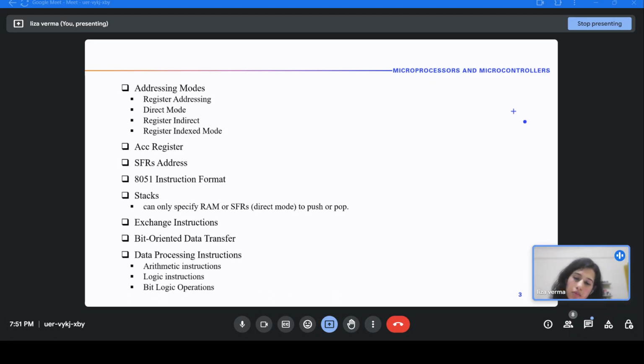You can decrement the accumulator or any number, but you can't decrement a data pointer. It's just the way 8051 is designed.